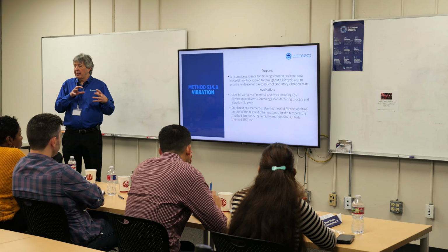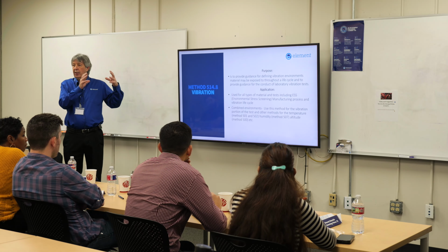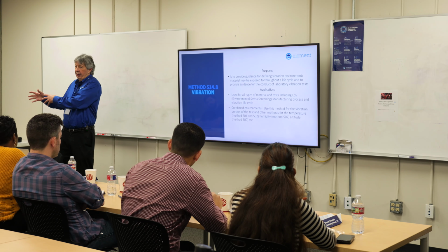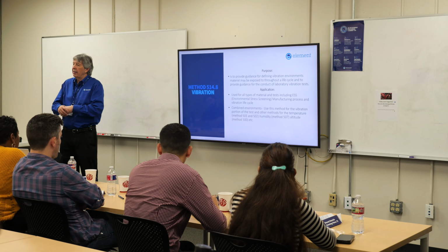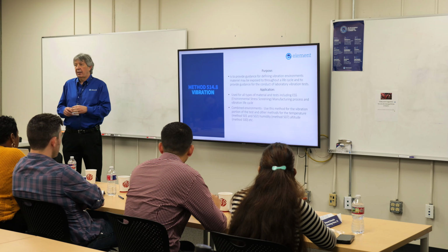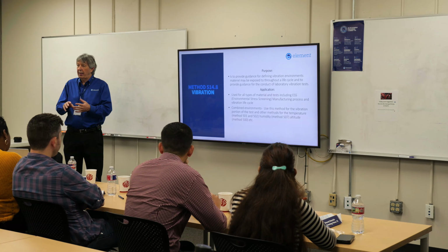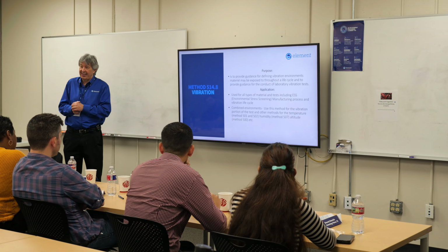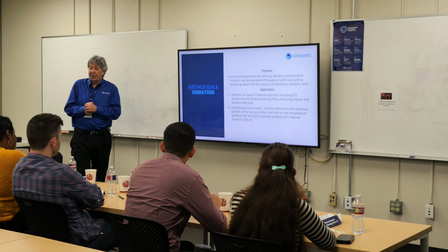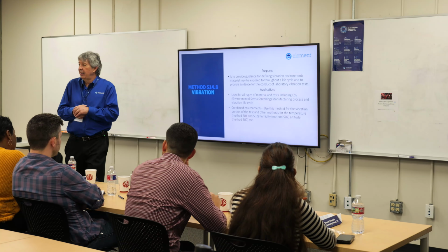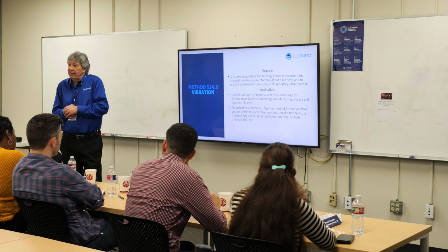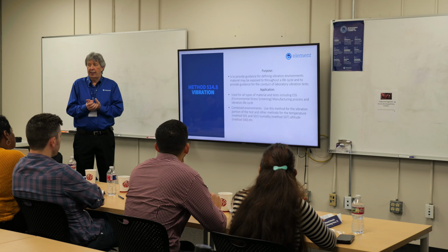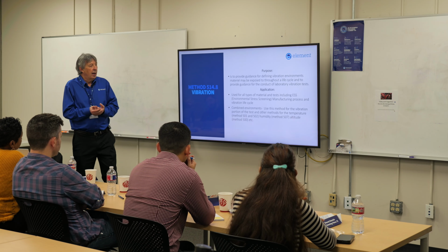So not sure what the cost is of the unit, but you're allowed to change units, fix units, do everything you want. Every test is a standalone test. So you can run transportation vibe, and then take a new unit and run op vibe, and you take a new unit. So you're allowed to do that. There's no accumulation of tests. So you can high temp, low temp, humidity, all can be all separate. You can have 28 separate units if you want. There's 28 methods, and I wouldn't suggest doing that because I'm sure your investors would not like that, but it should be fine. So every test is a standalone test inside MIL standard 810.